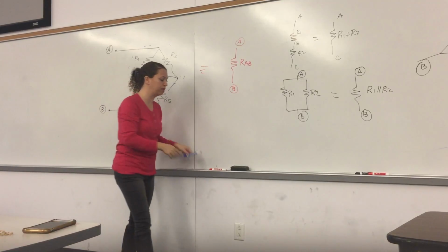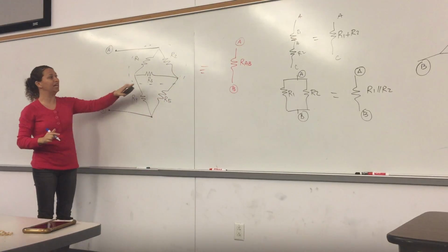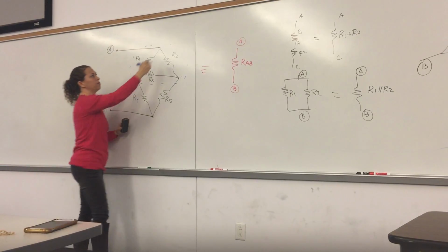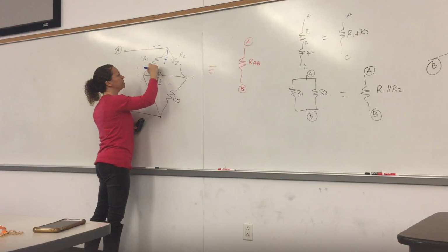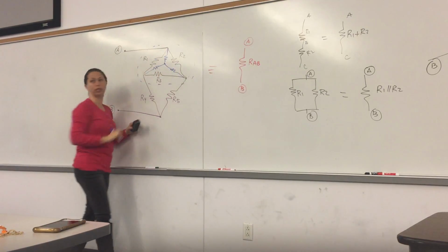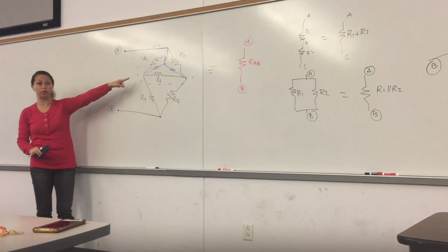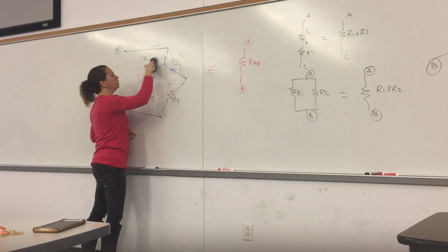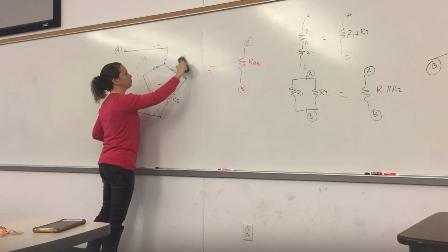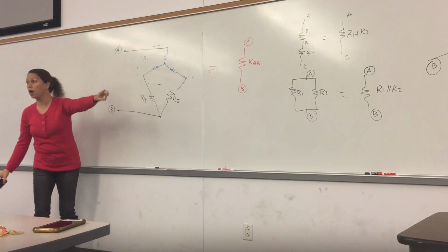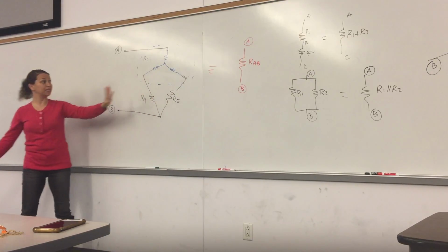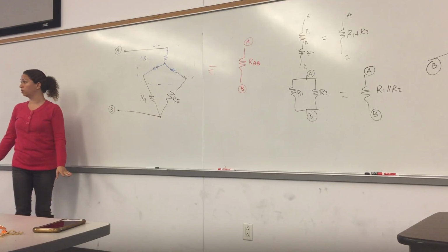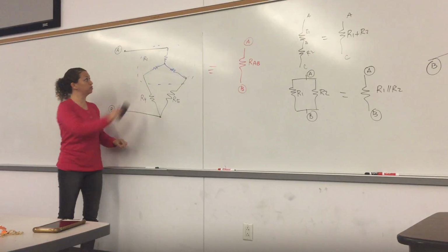So as usual, there are a couple of points. Now, let's see how we place this. Now, let's say I took R1, R2, and R3, okay? And then I convert it into its Y equivalent, okay? This is the new circuit, right? Now, this one, and this one, and this one are gone. I did delta to Y conversion, right? Now, does this solve my problems? Do I have series resistors there? Those two are series, right?